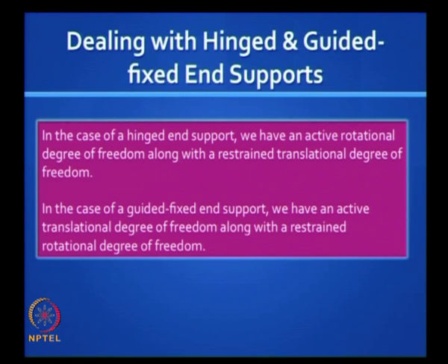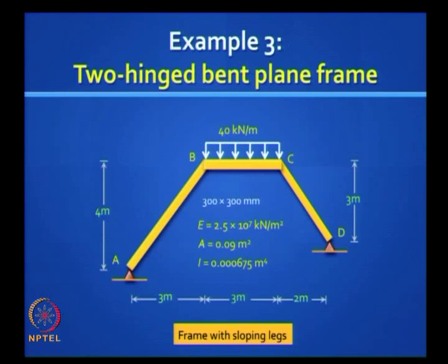Dealing with hinged and guided fixed supports is exactly similar to what we did for beams. You have to release some degrees of freedom. So let's take another frame problem. This is a bent frame. Remember we did this frame earlier by the slope deflection and moment distribution methods, but here you will get slightly different answers.